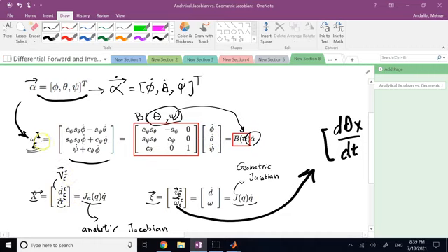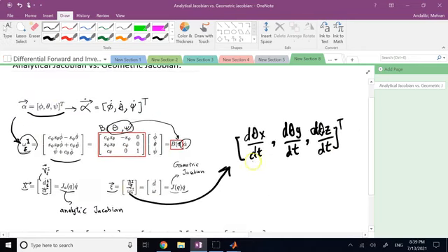So you see here, again, if the angles were absolute, the omega of end-effector in base would simply be 3 components, theta x dot, theta y dot, theta z dot, done. But now that they are Euler angles, it's not simply equal to these 3. It's equal to a matrix times those 3. We call it B. So it's B of alpha times alpha dot.